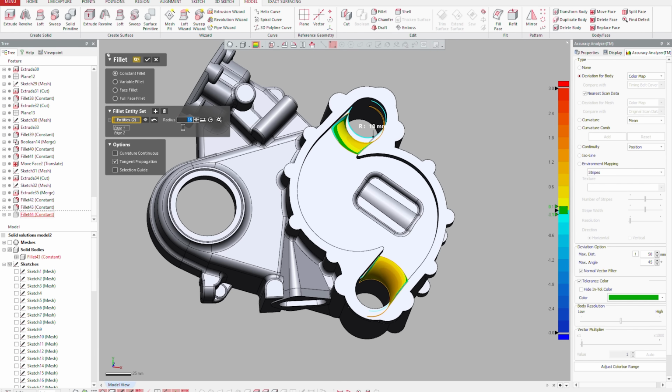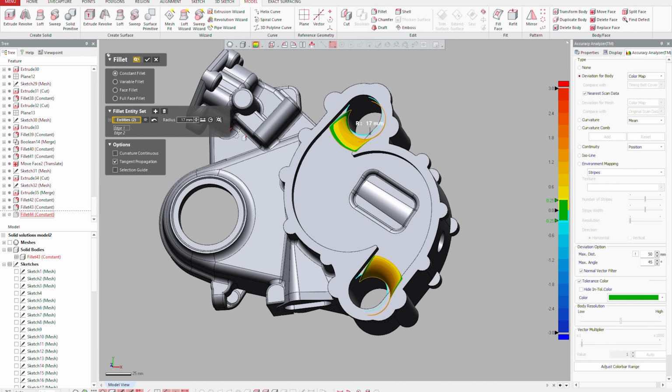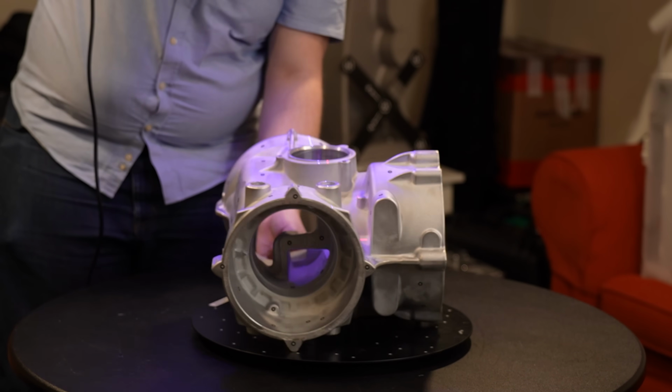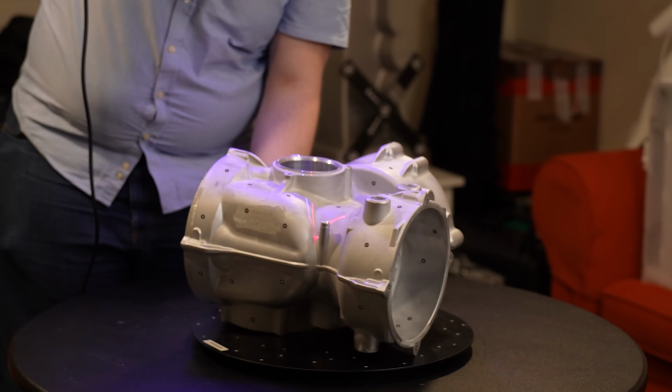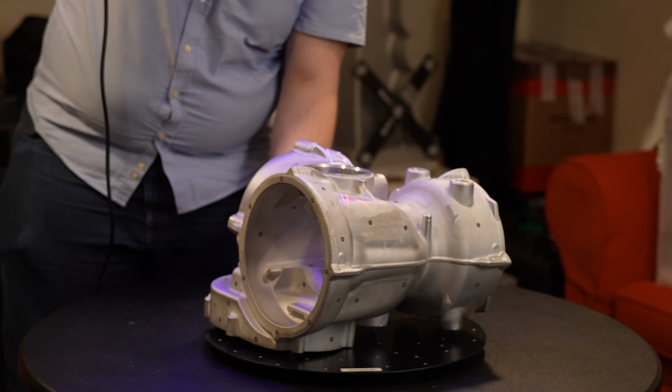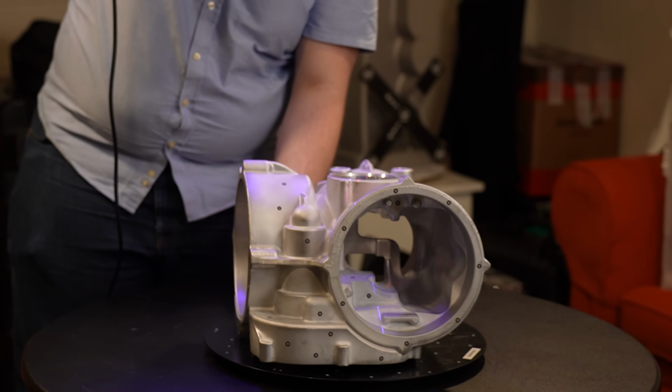Scan data can also be used for remanufacture, so you can just scan something and reproduce it from the model itself. You can also use it a lot for inspection, especially if it's done on what's called a metrology or high accuracy scanner. We can measure and check the quality control, check against tolerances, drawings and so on, and see if the part's been manufactured correctly.